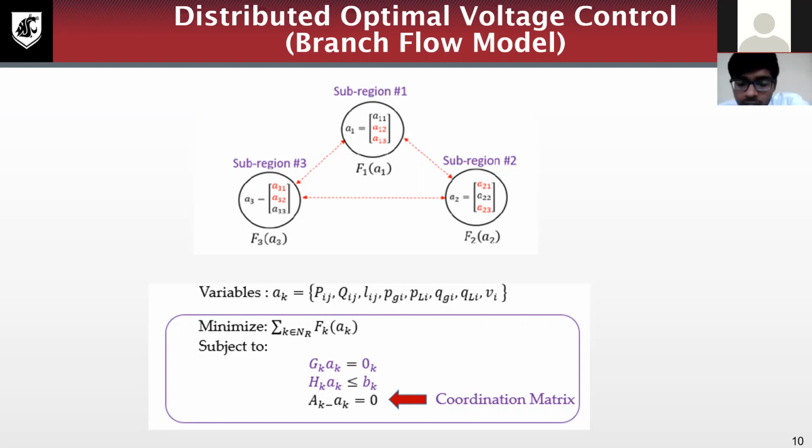And once you solve the problem, you have to check that the optimal solution that you get really lies within the feasible AC space of the power system network. That means you have to check that from the solution you can trace back the bus voltage magnitudes as well as its angles and the power injections in each of the buses.